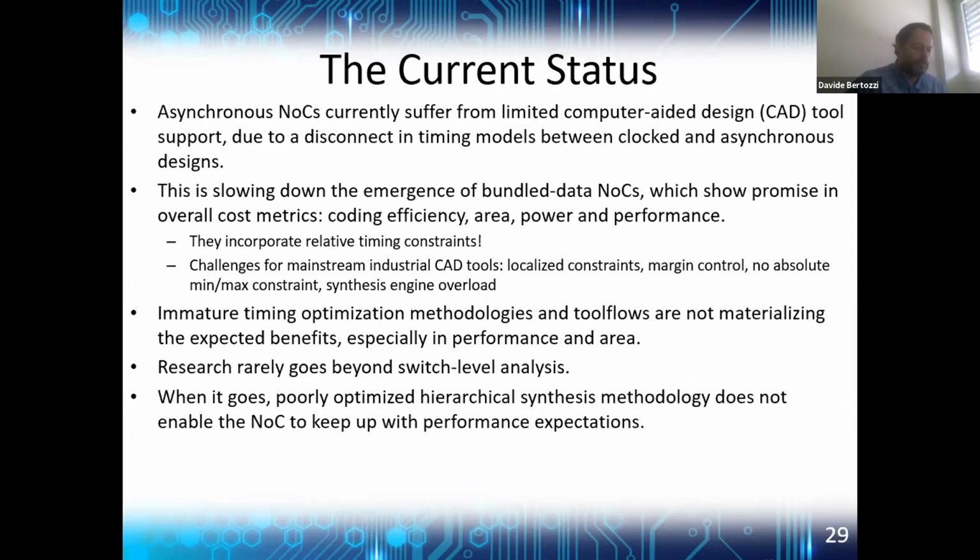Another main issue with asynchronous NoCs is that they currently suffer from limited CAD tool support. And this is fundamentally due to the different nature and optimization requirements of asynchronous timing constraints. For this reason, the onset of bundled data NoCs is only very slow nowadays, although these bundled data NoCs show promise in overall cost metrics: coding efficiency, area, power, and performance.